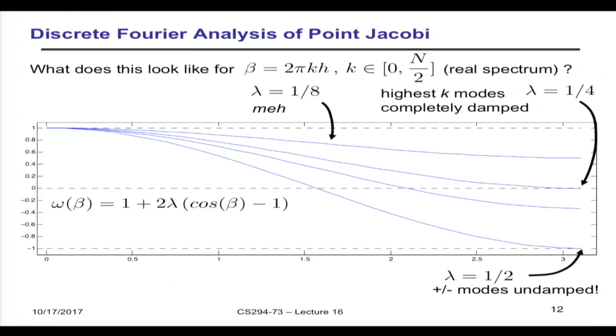So you might take one sweep of one, then a sweep of another, try to iterate around and get all of that error down, but you're not going to win, because in the end, this here is not damping the error at all. The smoothest wave numbers you have, and the finer the resolution is, the more you have to iterate on it to get that error to go away.